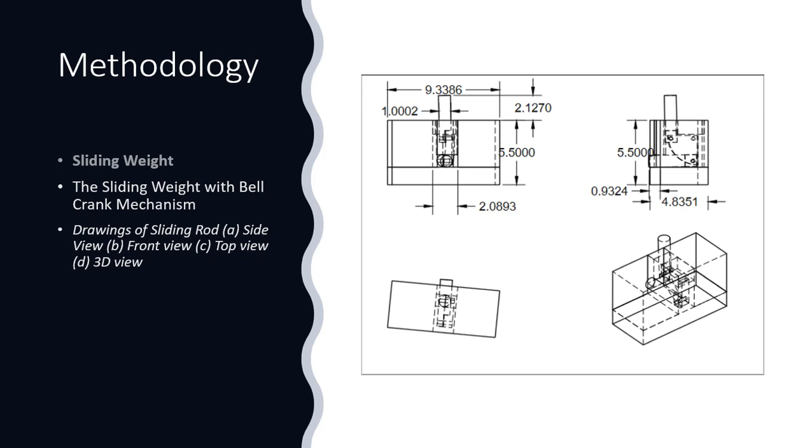So when the stopper engages with one lever of the bell crank mechanism, it lifts the weight from the sliding assembly to the required height. When the upper lever touches the upper part of the sliding assembly, it becomes pressed, and the lever pointing towards the stopper of the machine automatically moves through 90 degrees inside, and it automatically becomes disengaged.